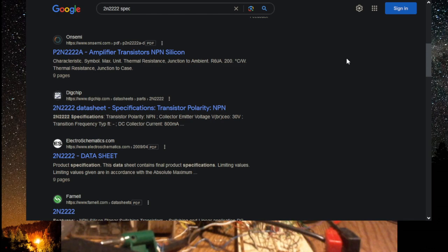I don't exactly know, but those adjustments with that micrometer, when you're changing the mirror, are so small. One micrometer is 1,000 nanometers, and the wavelength of the ultraviolet is in the nanometer range. We're talking tens of nanometers. So I thought, how am I going to do that? I'm going to use gear reduction ratio, and I'm going to use the micrometer to control a longitudinal axis to get gear reduction, and that's a whole other ball of wax.